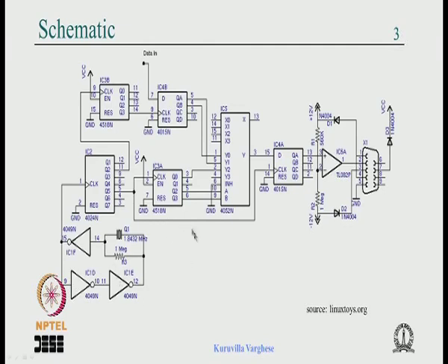So if you had to design a finite state machine, now when we described the finite state machine, we said you could describe that in a hardware description language, and the tool will make the next state logic and output logic. This was not possible with schematic capture. You need to draw the state diagram, make the truth table, minimize it, and then implement those minimized equations using gates and flip flops and so on. So this was external; you work externally and bring the design into the schematic capture.